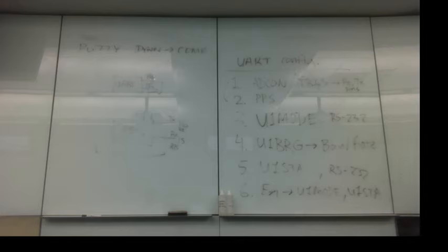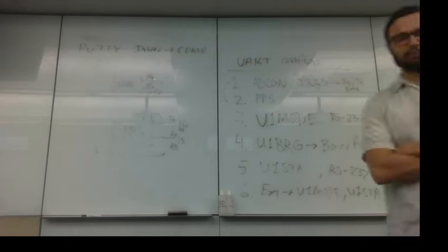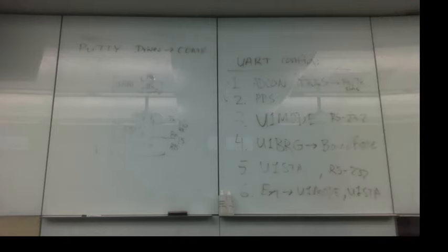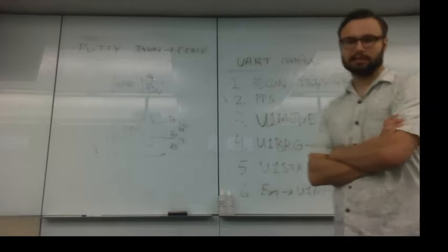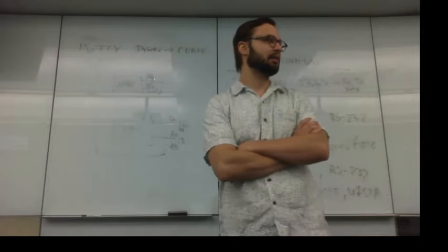And that's what, when you type in a terminal server, you're typing ASCII characters. So you're typing bytes at a time. If you type an A, that's 8 bits. And so you can send and receive bytes at a time. You could also send and receive number data, and you could send chunks of number data bytes at a time. You can choose what you want that number data to represent, but it just has to be agreed upon on either side of it.